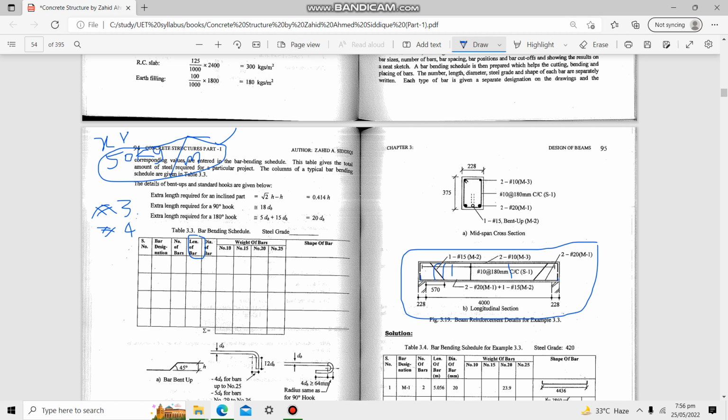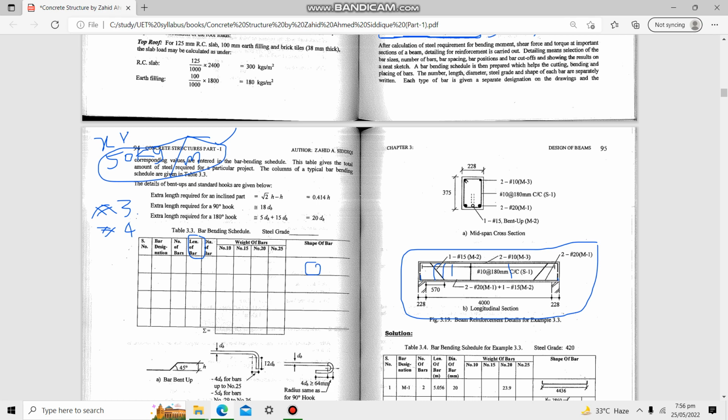Like if I talk about the stirrups, here we provide this bend in the stirrup at an angle of 135 degrees for the purpose of anchorage, so that the stirrup is able to hold the longitudinal bars and prevent these bars from slippage, and it can protect the longitudinal bars from seismic actions, which is the earthquake loading.